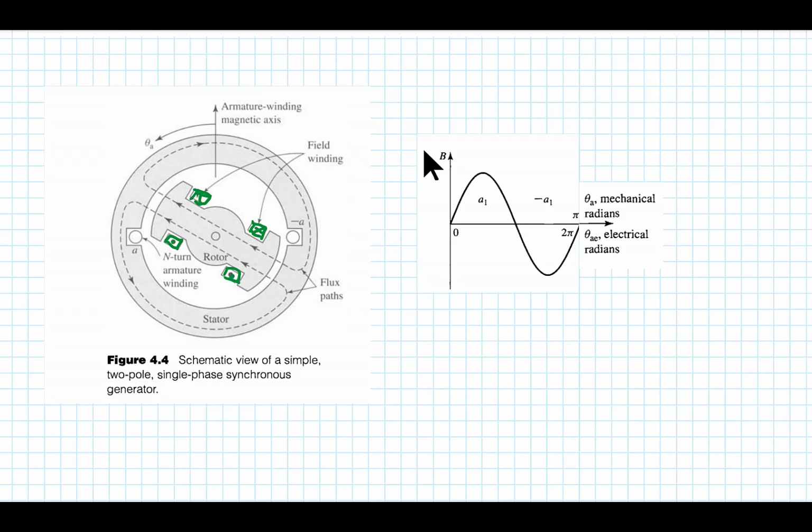So the current is coming in here through slip rings, wrapping around, and coming out here, the winding with the field current in it. There are going to be a number of turns, which we'll refer to as field turns, NF. And the current going in here we'll refer to as the field current, IF. There are quite a few field turns, probably hundreds to thousands of turns on any synchronous machine.